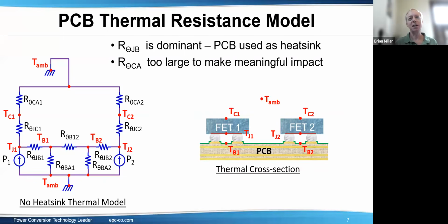Let's see, the resistance does go up with temperature, almost exactly the same kind of curve as MOSFETs. That could be one thing. You could be fine when it starts, then temperature goes up a little bit, and the resistance, with both GaN and MOSFETs, goes up about 1.8x going from say 25 degrees C to maybe 125 degrees C. That can maybe cause the problem.